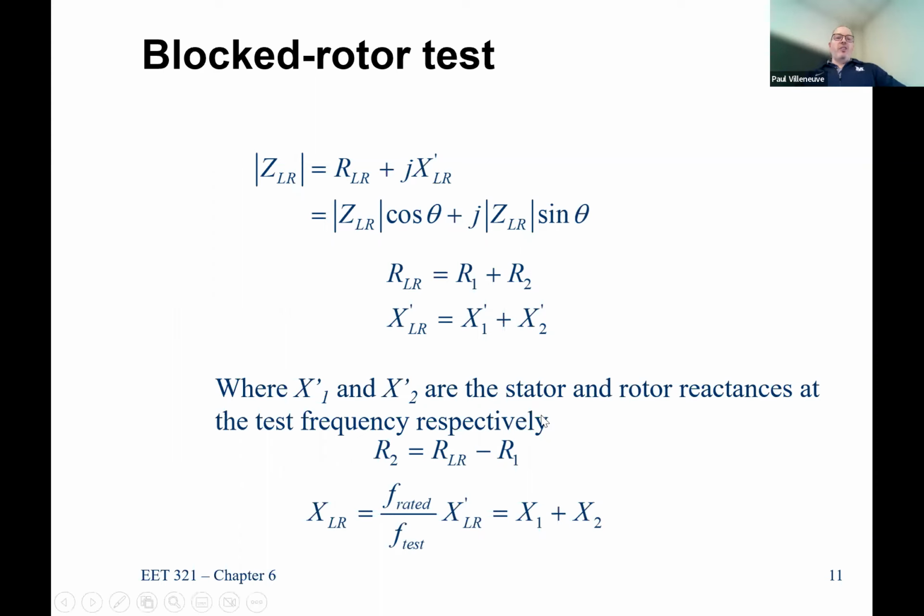But one of the things you can do is run your frequency lower than the rated frequency. Because remember, if my stator field is running along at 3,600 RPM or 1,800 RPM, whatever the number of poles are, that's spinning along really fast. The dphi/dt is quite high. If I drop my frequency, dphi/dt is going to drop as well. So if I can, I'm actually going to perform the test not at 60 hertz, but maybe 30 hertz, maybe 20 hertz, maybe 10 hertz, whatever value reduces it. So I don't have to work as hard.